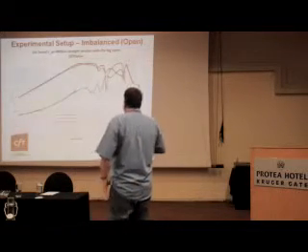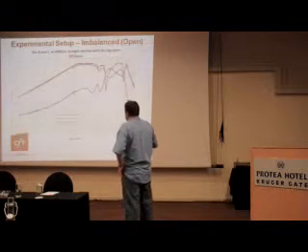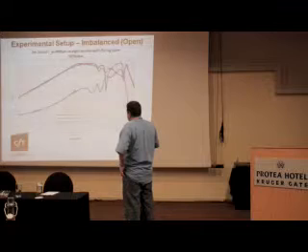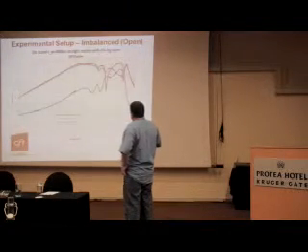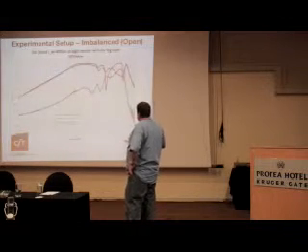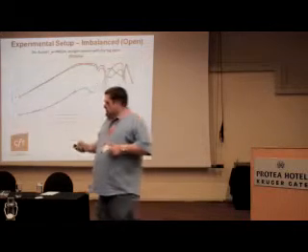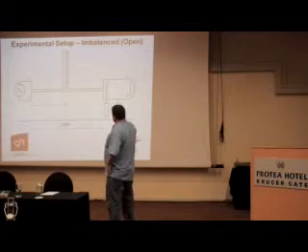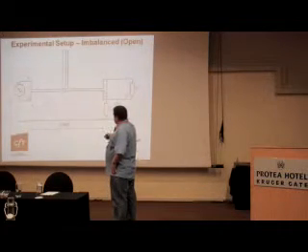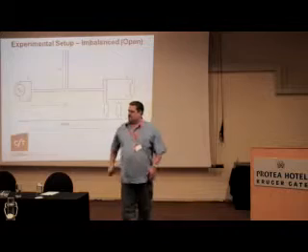But the interesting thing is that from a fairly high frequency, 10 megahertz in this case, we started getting coupling, and we started getting a channel even though the switch has been switched off. There is coupling between this neutral line and this earth line, and you can pick it up on the MIMO channels at the end.